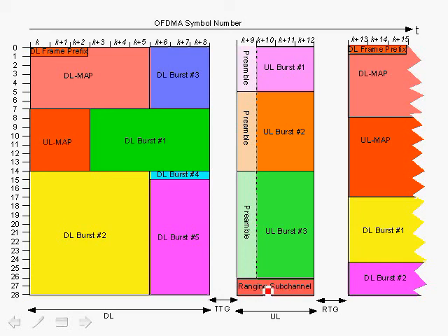And again, notice that the ranging subchannel corresponds to a particular location which is specified in the uplink map, and it corresponds to a number of time slots of OFDM symbols. So you have both specification in terms of subchannel and slots in terms of the OFDM symbols across in this direction at a time. So this information is available to the subscribers so that they can send the CDMA code within the particular slot back to the base station.